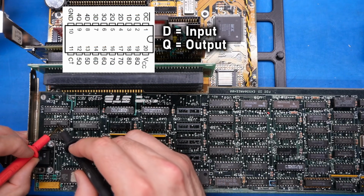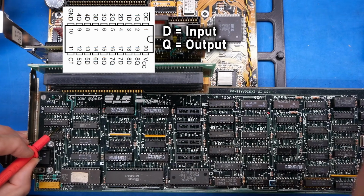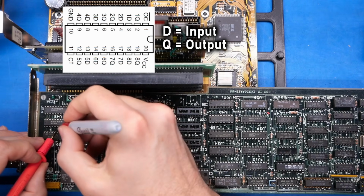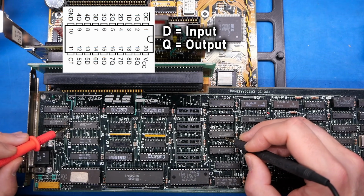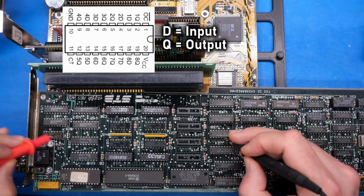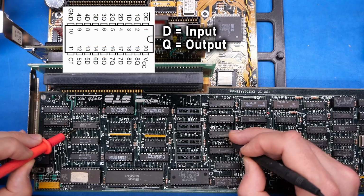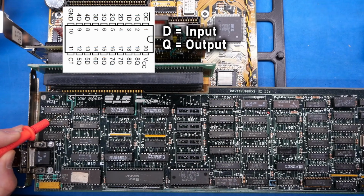Okay, but on this chip over here, the pin we're on is 17, and that's an input. I just have the data sheet up on the screen. I know you can't see it. So this one here is used as an input. So I'm going to put a dot over here because that is a suspect. Okay, so now I'm on that chip there. Let's see if we can figure out where over here it's hooked up. Okay, it's that pin right there, which is also an input. So that's good. So we know that that's suspicious. And I'm assuming it's going to be on this chip on an output pin, and it is. That's 5Q. Then this RAM chip here is connected to this other flip-flop there.